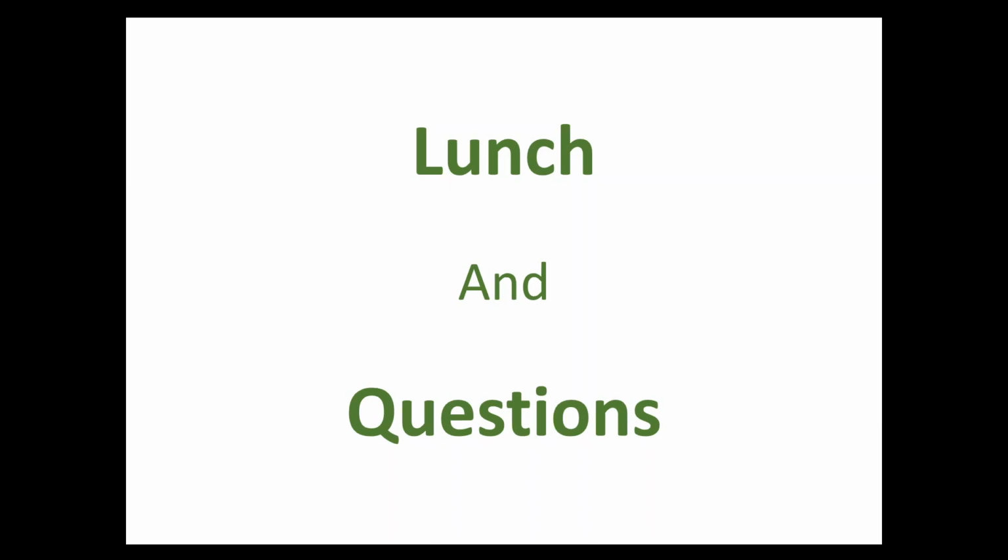A couple of answers there. For failures that find you, typically what we've agreed on in the industry is to say that those that come to the surface are of a more severe nature than those that are running underground that you have to try and find. So the time to become aware of those leaks is assumed to be shorter. There are some industry guidelines in the software and the report that goes along with it. For a main break on an 8-inch main, it's probably not going to be weeks and weeks, but just a couple of days before this became a real issue.